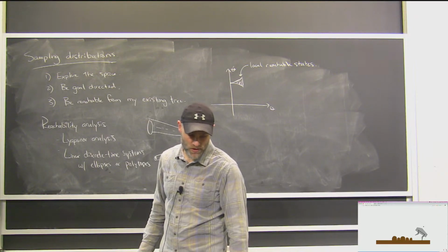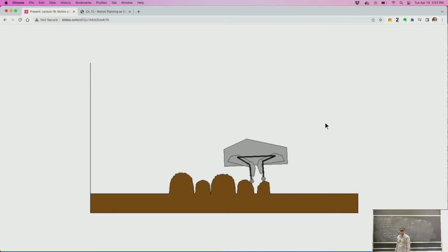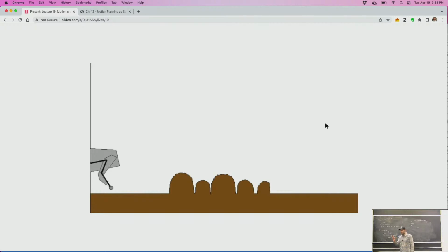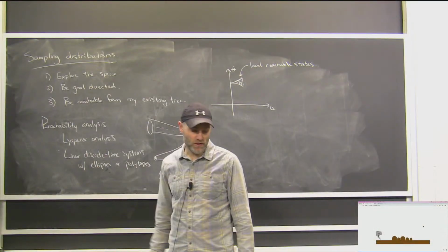Back in the day, that was enough to plan dynamic trajectories of Little Dog bounding over rough terrain, which we just couldn't write a controller for ourselves. We used only an approximate model of the robot. That was definitely an approximation, an approximate notion of the terrain, but for a particular terrain, we could plan a specific set of bounding gaits in order to bound over that terrain. Too slowly to run online, right? So all the MPC stuff that's been happening more recently in quadrupeds is much faster than this. This was an offline computation. We were happy to find it ever.